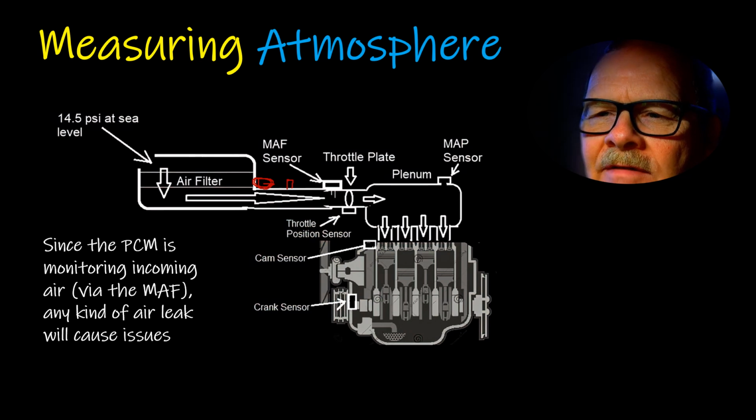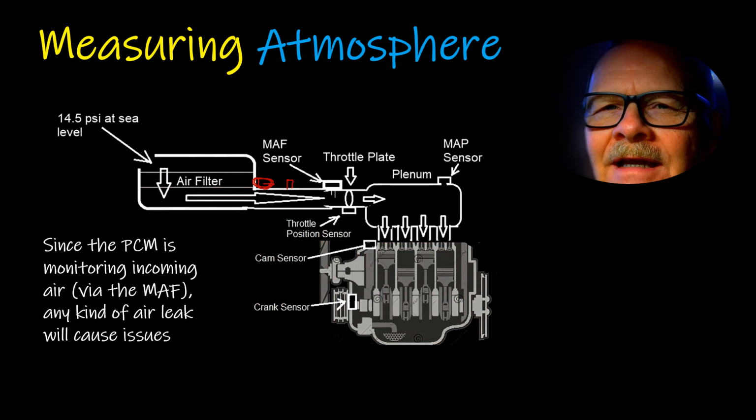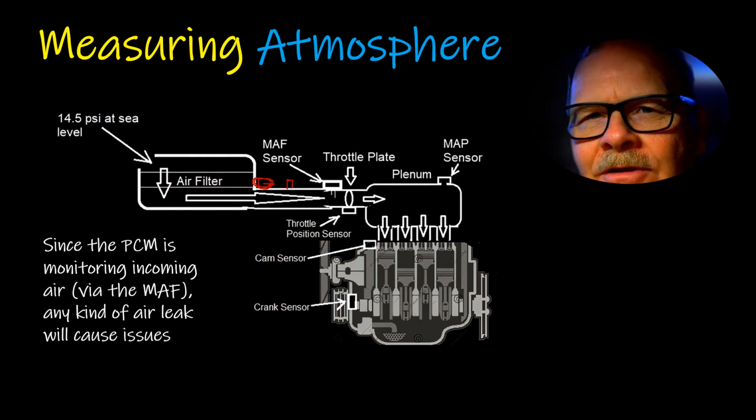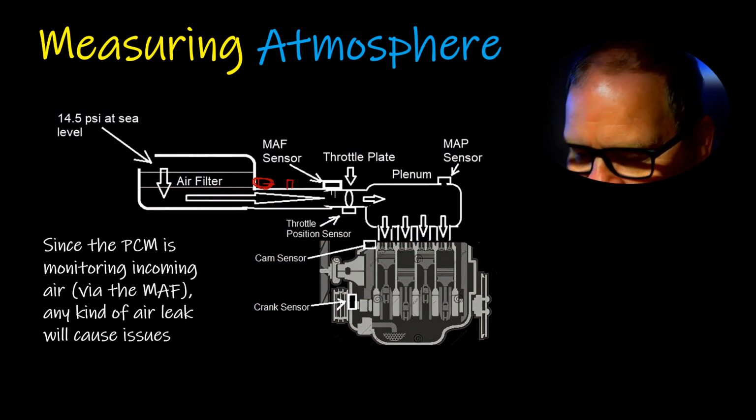And so the PCV closure hose, that air that's going through the engine by way of the PCV system is also metered. And you can take the oil filler cap off of an engine and watch your fuel trim numbers change, because you're letting unmetered air in through the oil filler cap. Imagine yourself with a fuel trim problem being caused by somebody having removed the gasket from the oil filler cap. Wouldn't that be a good bug to plant for your students if you were teaching automotive?